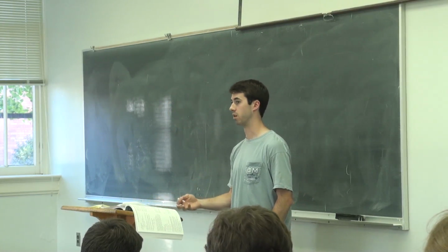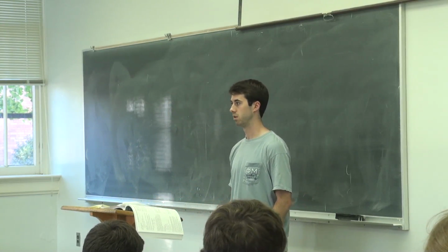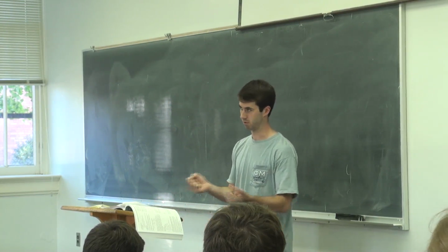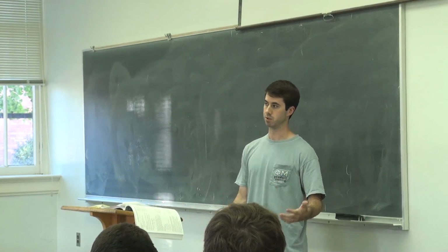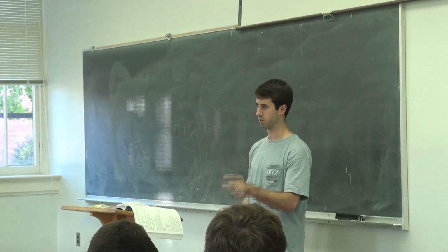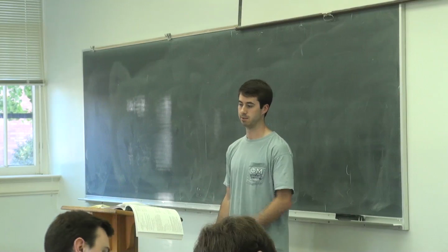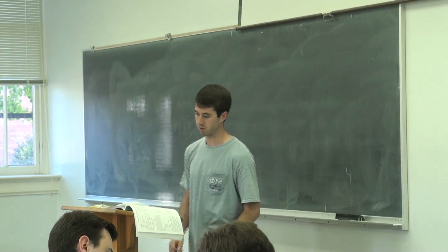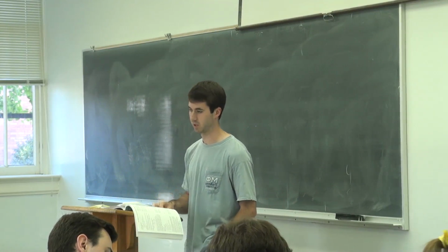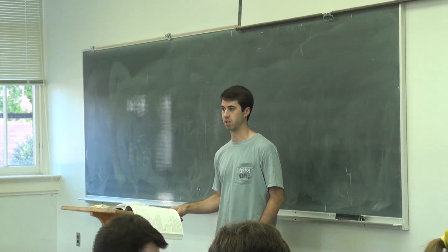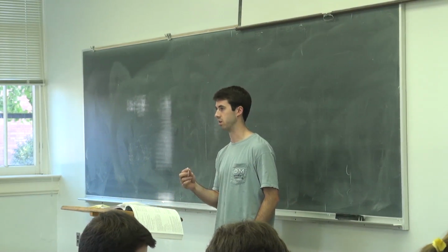In reality, the area would change because it's being stretched. Engineering stress just calculates whatever the load is divided by whatever the initial area was. That's fine for the most part, as long as you're in that elastic region. Once you get out of that, you start having changes to your cross-sectional area.